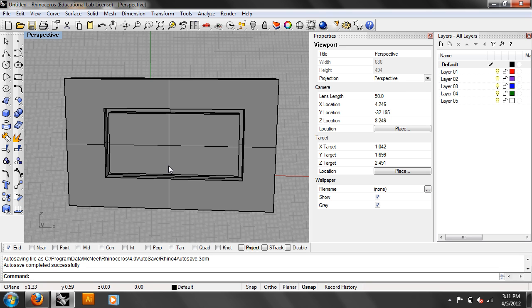With a block from AutoCAD into Rhino, how do you make the block turn off? I think you can just explode it or ungroup it. I can't remember what it wants to be. Did you just put a block in? No, I put in the plans of the house that you gave us, and the windows and doors are all a block. Okay. I think there may even be a way of just exploding it or embedding it.